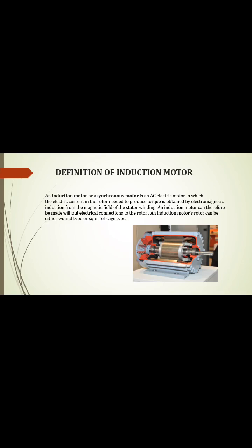Here we can see the definition of induction motor. An induction motor or asynchronous motor is an AC electric motor which works on the principle of electromagnetic induction. In this motor, the electric current in the rotor needed to produce the torque is obtained by electromagnetic induction from the magnetic field of the stator winding. Therefore, the induction motor can be made without electrical connections to the rotor. An induction motor's rotor can be either wound type or squirrel cage type.